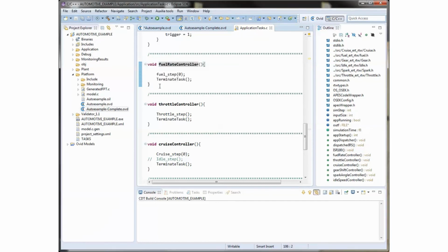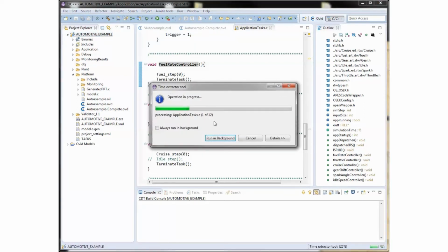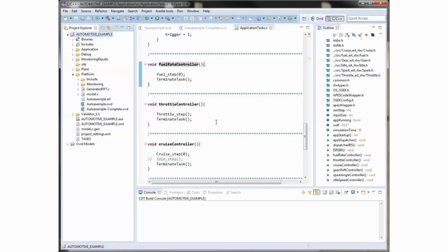The tool determines first the places in the code where platform behavior needs to be executed. By default, these are all the source lines with access to global variables used in different tasks or to hardware registers. The user can specify different rules in this respect. Then the time extractor tool determines execution time estimates based on the results of the time tracer plugin. These are the inputs to the time weaver and platform weaver tools.